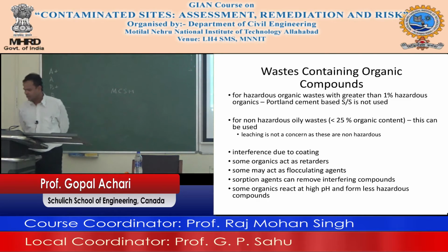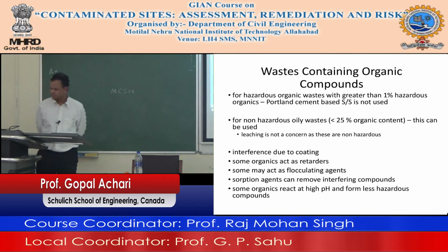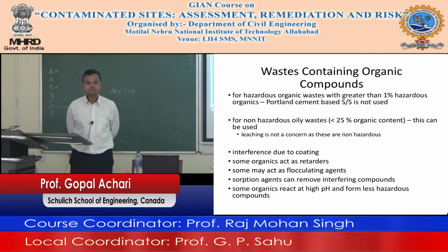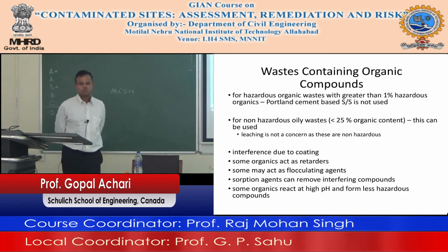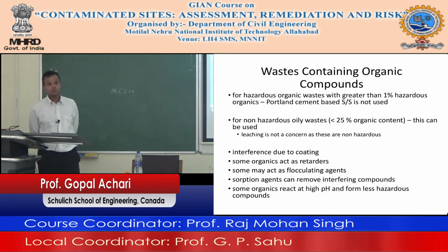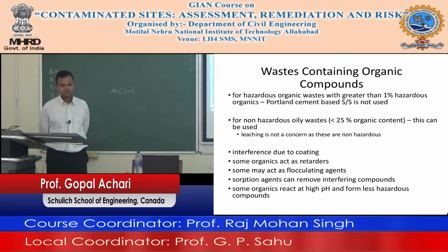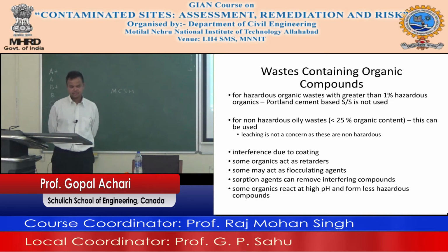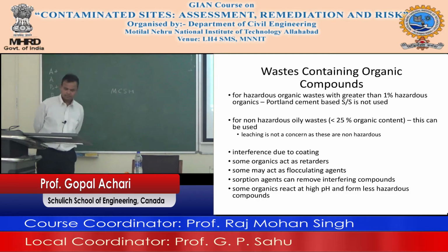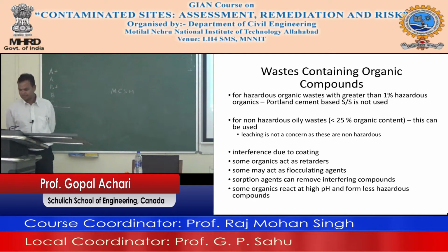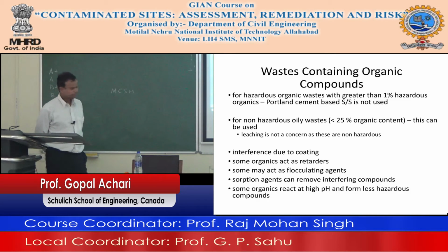And roughly, with greater than 1% hazardous organic, you should not use it. Straight as that. If you have 1% or more hazardous organic that you want to fix, cement is not the thing to do, because cement will not set. And even if it does, it might still leach out. For hazardous, okay? For non-hazardous, the leaching is not such a big concern, and you can use it.